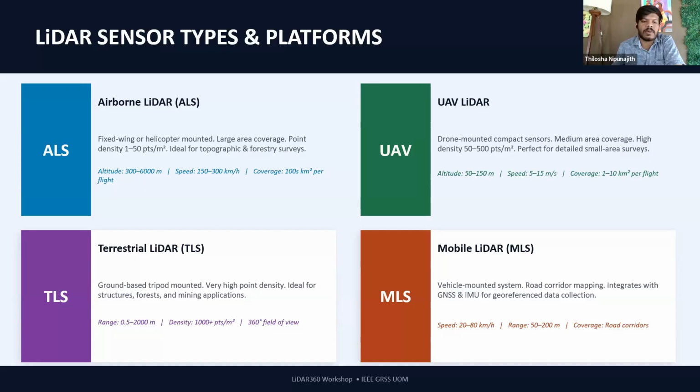To derive such accurate ground level geospatial data, it requires technologies like terrestrial laser scanning. Using ALS is also possible, but when it comes to ALS and TLS, TLS is the most accurate method. It can be highly dense point cloud on a ground basis, so your point cloud might not omit any ground level data, unlike the ALS method.